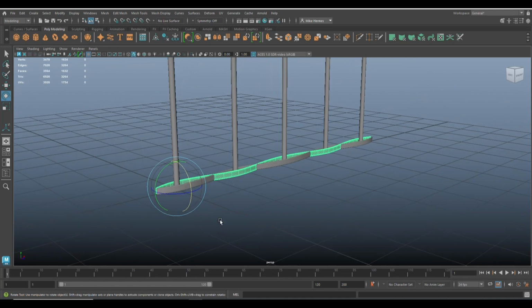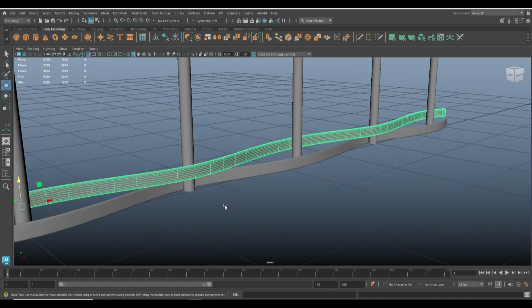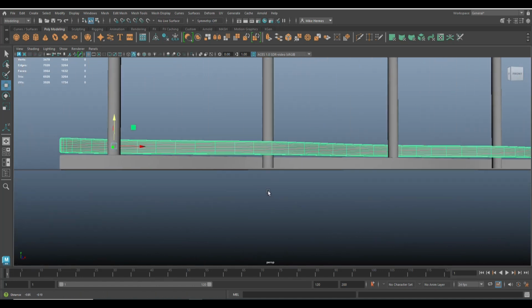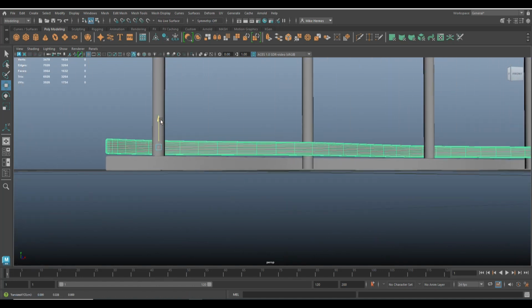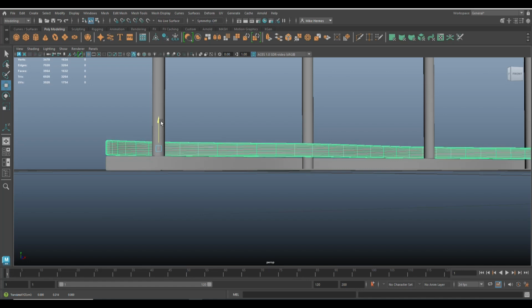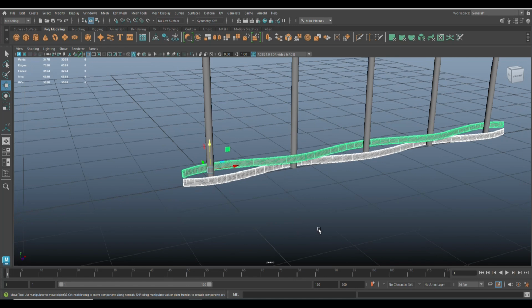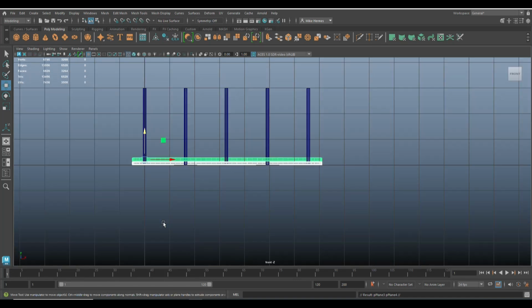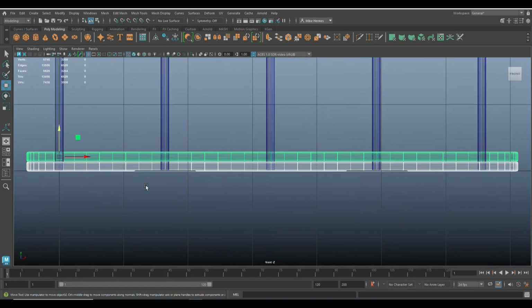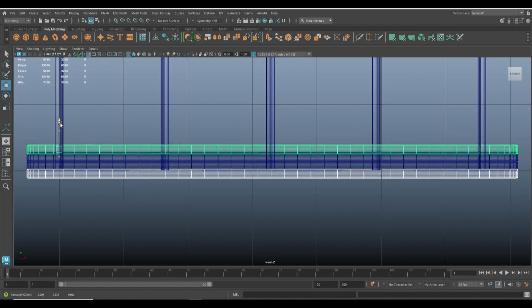All right, lift it up so they're not touching, at least not too clearly, like so. Yeah, cool. And then you drag select both, you hit Control D to duplicate. Let's jump in here, F to frame, you push them up.